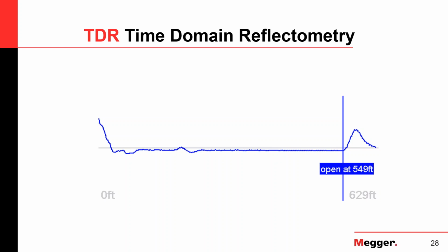It is important that you have an expectation when you go out there. If you know the cable is 1,000 feet long and the TDR tells you 980, does this meet your expectation? Or does it not? Is it close to the 1,000 feet, or do you have a very exotic fault right there at 980, like an open conductor, and you don't actually see the physical end of the cable? But 980, 990 out of 1,000, that sounds pretty good as a first approximation. So you have to have an expectation.